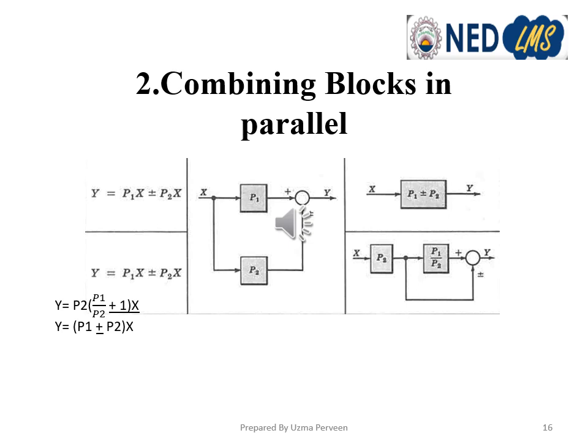Here in the second transformation, we can simplify it as the forward path and a parallel forward path with a transfer function 1. When we directly connect some points, it will have a transfer function of 1. So it is P1 upon P2 plus 1, and this whole is multiplying the series combination of P2 and x. So we'll multiply P1 upon P2 plus 1 by P2 x, and when we expand this bracket, it will become y equals P2 multiplied by P1 upon P2, so that P2 will be cancelled, plus P2 multiplied by x, and it will become y equals P1 plus or minus P2 into x.